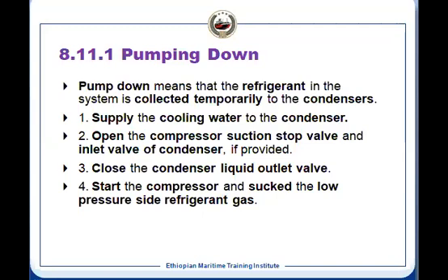We have a compressor, and after the compressor we have the oil separator, and the separated oil goes back to the compressor, and then the refrigerant goes to the condenser. Let us consider that the condenser and the receiver are the same, meaning the lower part of the condenser is the receiver.